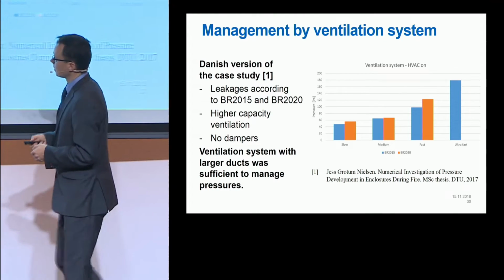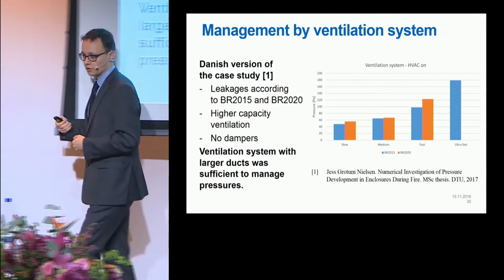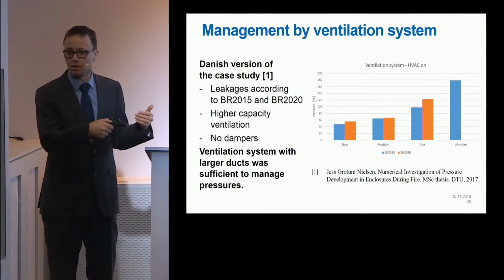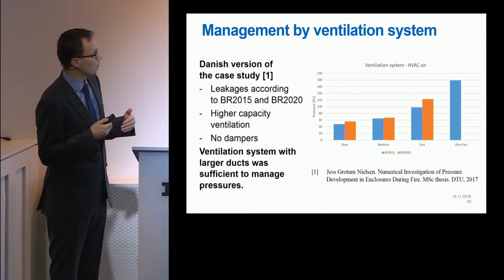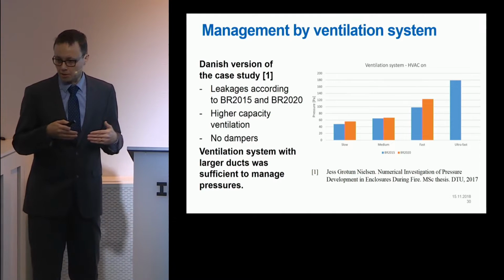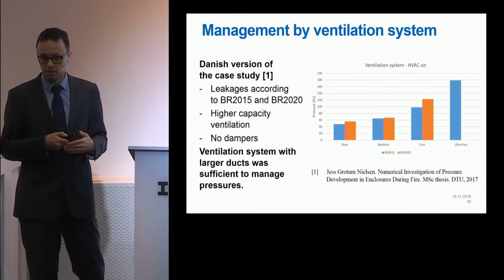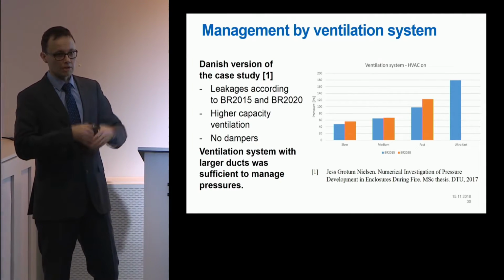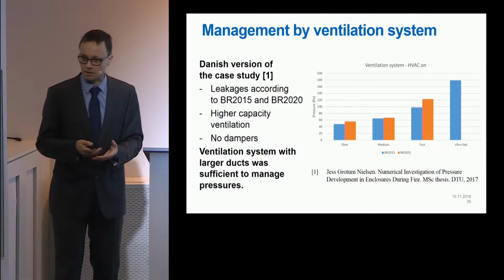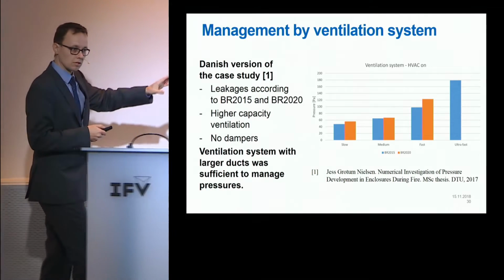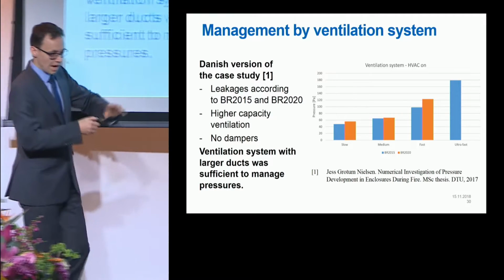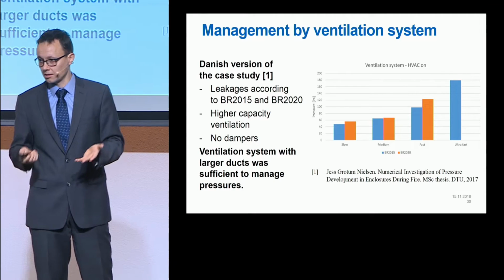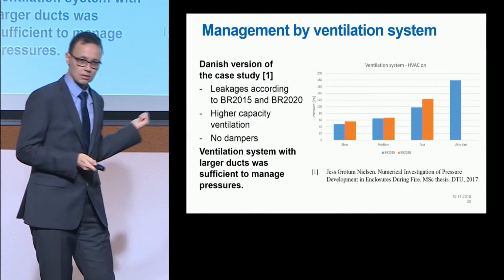His conclusion was that actually, using the Danish standard, ventilation ductwork can pretty well serve as a pressure relief path. Okay, what we learn is that it depends on the sizing of the ventilation system. In their regulation, the design guide, they clearly have bigger ducts, more volume flow, or bigger capacity for the ventilation system than in the Finnish buildings.